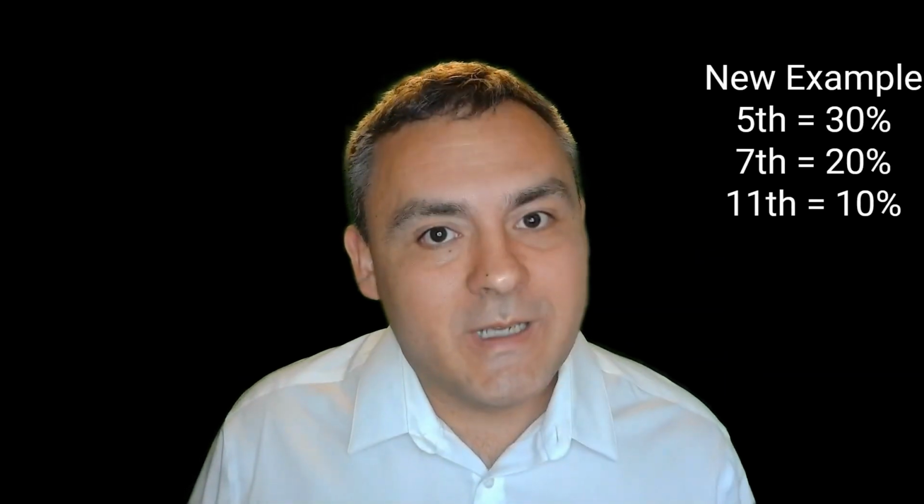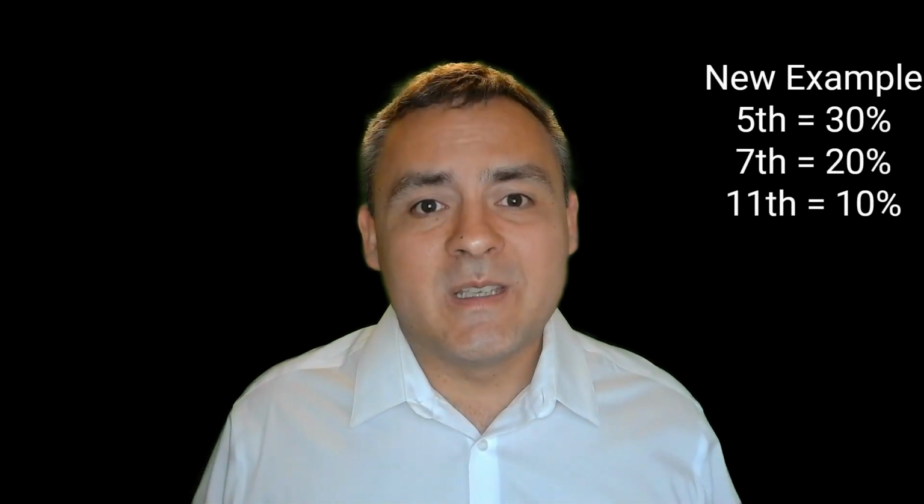Remember, from the first video, I mentioned that IEEE 519 wants to keep total harmonic distortion to less than 5%. The THDV for this example is 3.74%. I say this to say we knew in advance that harmonics would have a benign effect on the conductor sizing. All right, just for kicks, let's assume our fifth is 30%, our seventh is 20%, and our 11th is 10%. How much current will we draw at this point? The answer is 276.28 amps. Our 4-aught conductor will overheat for these conditions because we know its ampacity is only 260 amps.